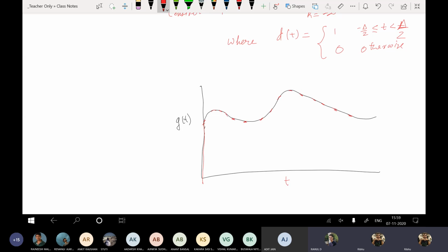Did anyone look at AD633? I told you to do this in AM. Sir, multiplier, right? Yes, AD633 is a multiplier. And so you can sample using the multiplier, and basically you will be multiplying a rectangular wave with an extremely small duty cycle with the signal of interest.